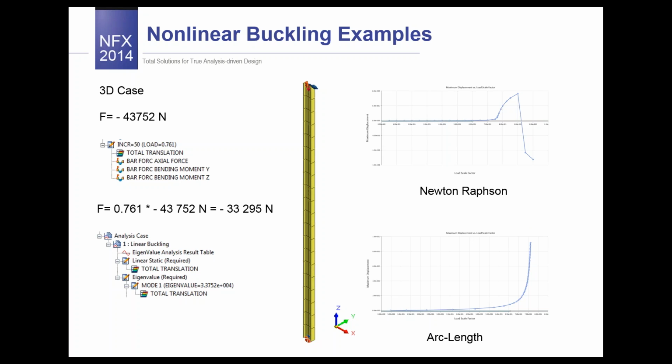So this time we are changing the environment. For the previous buckling calculation, our case was defined as 2D. Right now we will perform a 3D case, and we will change the value of the force, and we will see what will happen for the Newton-Raphson result and for the arc length, for example. Actually, the solution has been provided.